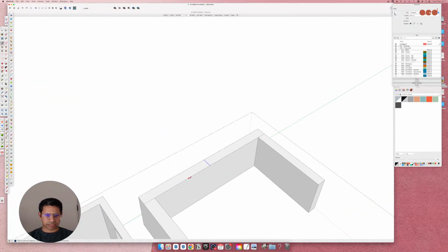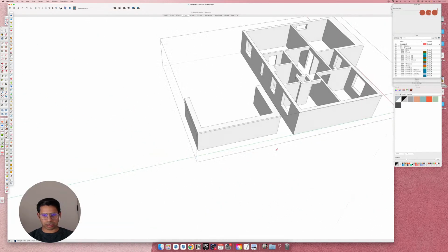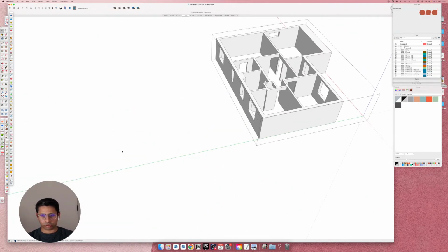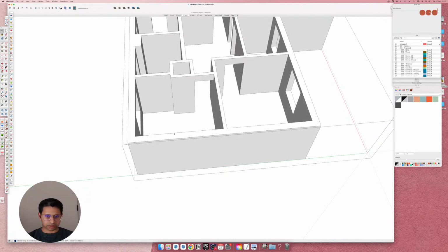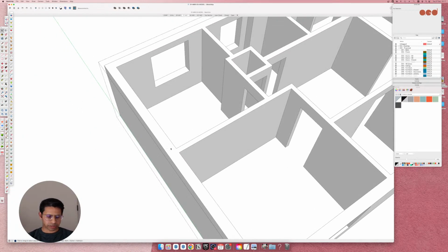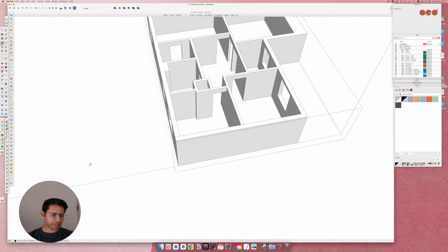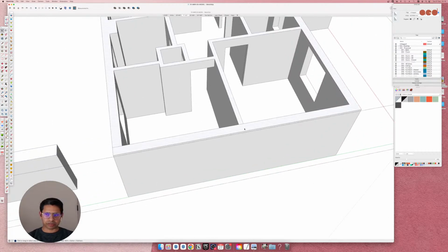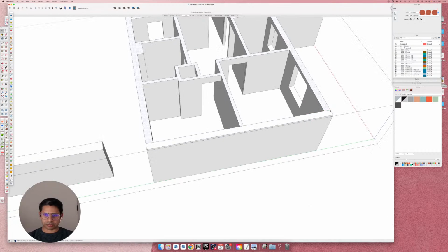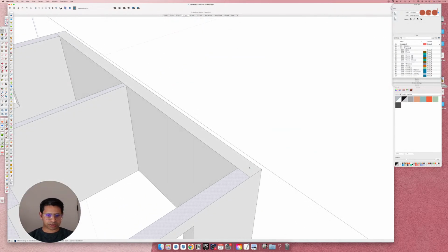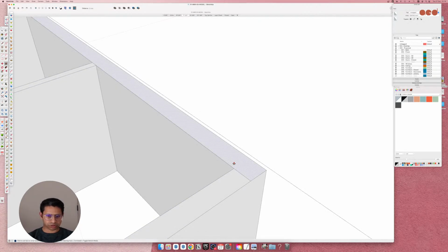But there is another way to do the gable end for a wall like this, where there are multiple walls returning from this end. Instead of creating the L shape or the return wall, you try and create this rectangle scenario here, which means you close all the edges and give it just a little bit of extrusion.